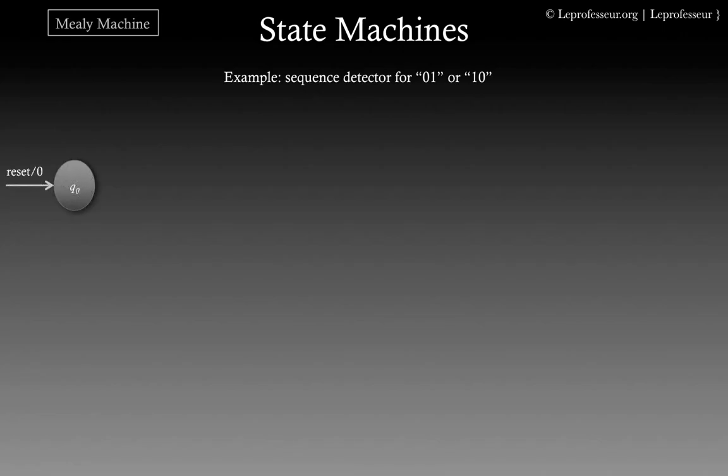So initially you are in reset. As soon as reset is deasserted, you reach a default first state. And in a Mealy machine, just by convention, on every arc we say input and output. So reset is the input, for example, here, and what is the output produced? Because you see, Mealy machine is very susceptible to input changes because it makes use of the input to produce the output, along with the state.